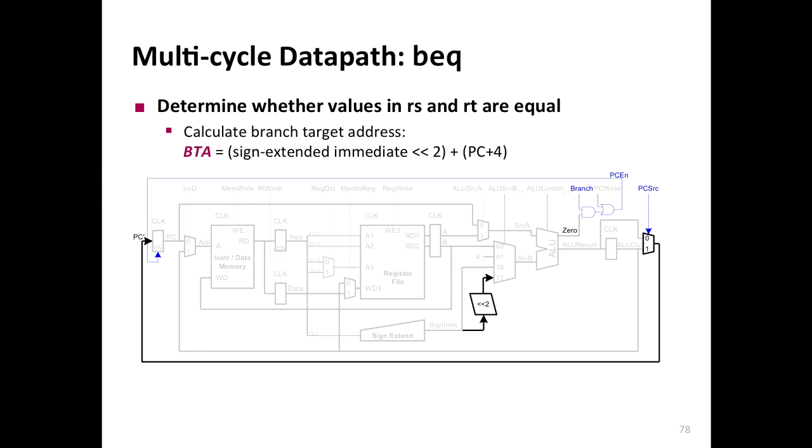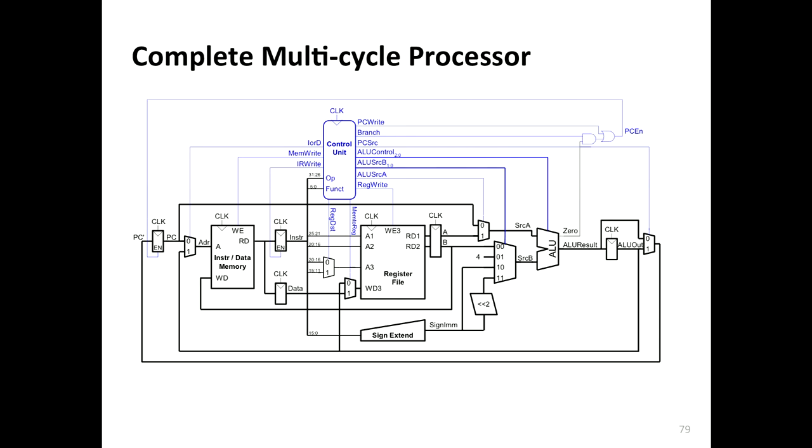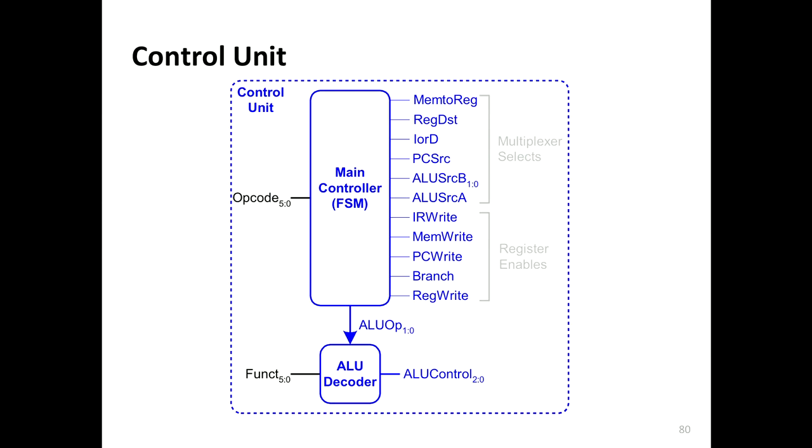Okay, is this all clear? Yes? Or you will do the reading to make it more clear. So basically, we've completed the multi-cycle processor, at least with the instructions that we have. So you need to generate the control unit, of course, that's important, right? And the control unit, in this case, is combinational. Given the opcodes, you generate all the signals. And of course, there's a finite state machine over here, basically given the opcode and the state that you have.